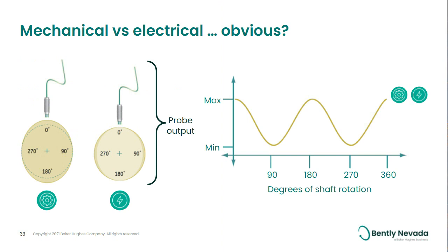So on the left, the shaft is oval shaped. So from a mechanical standpoint, it has runout. But from an electrical standpoint, it is perfectly fine. The shaft on the right is perfectly round. So from a mechanical standpoint, it's great. But electrically speaking, it's got some runout. Again, this is a purely mathematical example. It'd be difficult to do this in the field, but bear with me here.